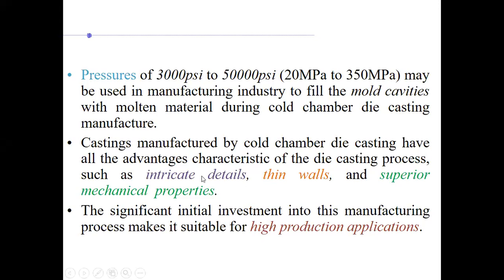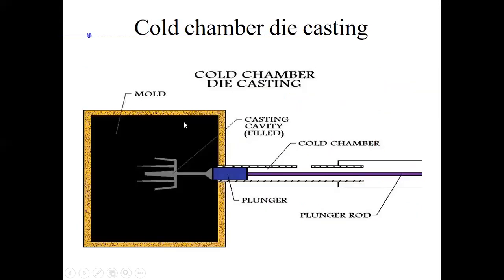The investment is high initially because to be able to design that mold requires a lot of research and development, to be able to come up with all the dimensions, considering all the parameters, thermal and mechanical structural parameters, all that. So that requires a lot of initial investment. But it will pay off when you're trying to use it for mass production, right?